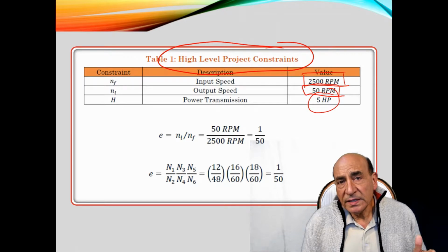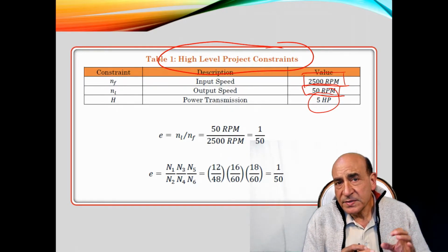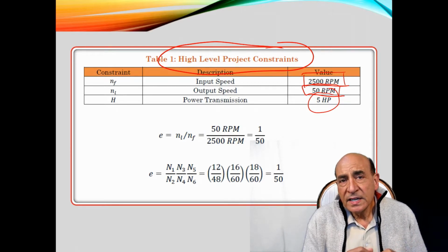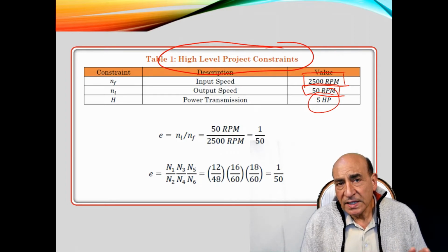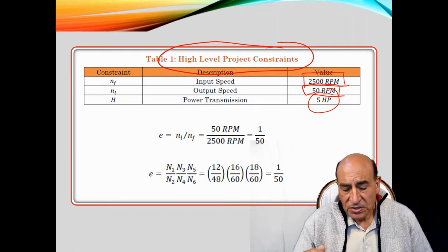in the speed would mean that, because the input speed is very high, you would have to come in with a small size gear with a smaller number of teeth that rotates very, very quickly. And then as you step down the speed, you have to transfer to larger and larger gears, to achieve that kind of gear train ratio that we are talking about.